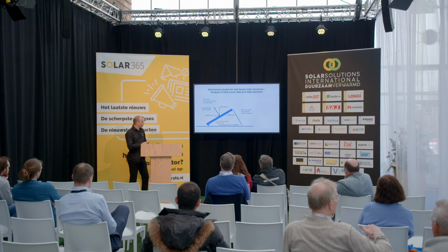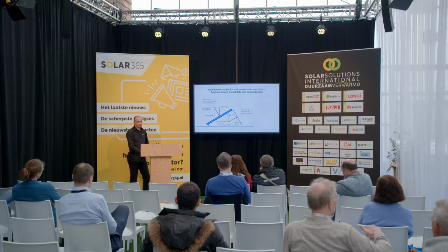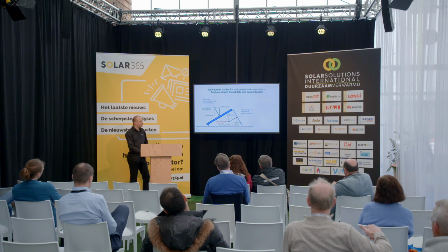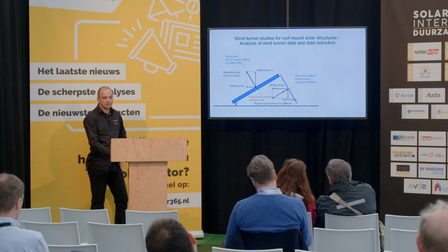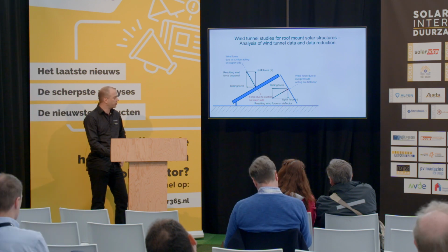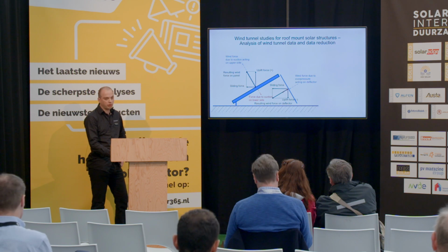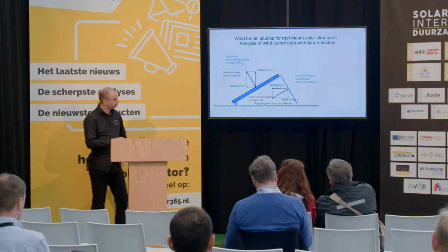Just briefly on the forces acting on solar panels and on deflectors, or in the case of east-west, acting on the east and west modules. The wind force is always perpendicular to the surface. There's usually an uplift on the PV panel, and on the deflector it can be a down force with a sliding load case, but it can also be an uplift force. So we usually have 2 components adding up in the horizontal direction, and the deflector compensates a little for the uplift force on the PV module.